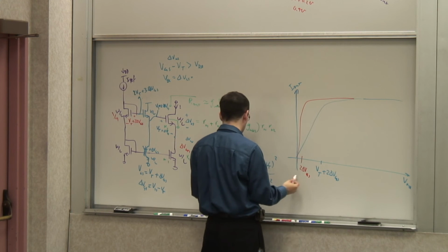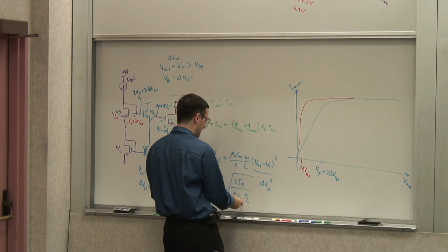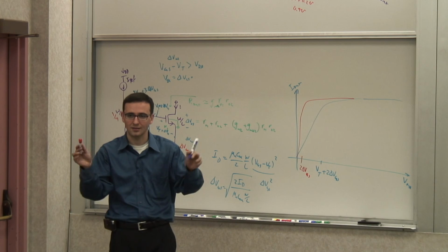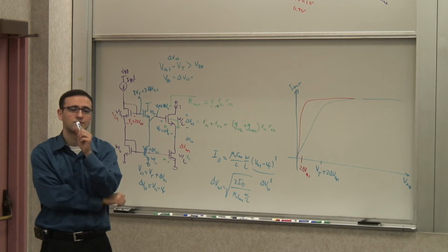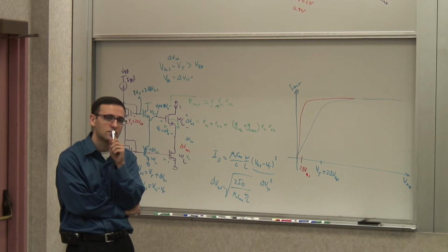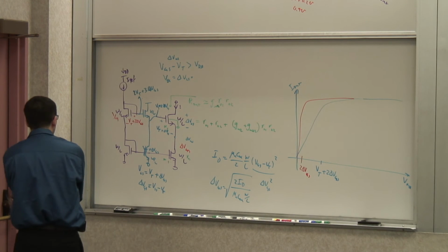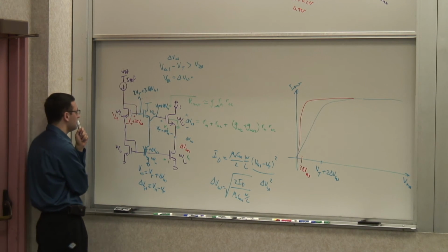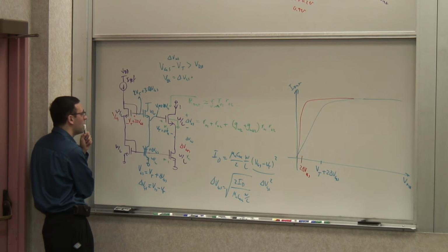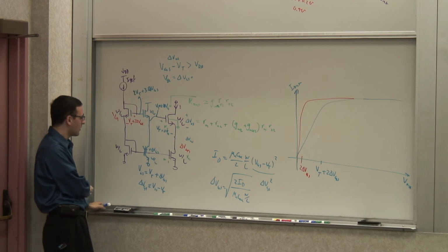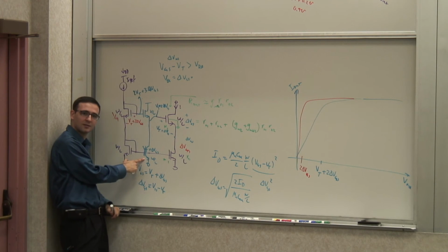And then if I really want to minimize this, I can also change my W over L of everything. Yes. Doesn't that change the current on the right side? On the which side? No. Wasn't you changing the VGS of the transistors on the right side, top right? Right. No, it won't, to first order, because the current in this branch is controlled here.